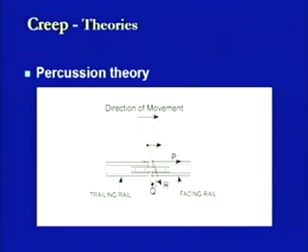Now, when this opening of the joint is created, these fish bolts will try to resist the movement of this rail section in the forward direction. When these two fish bolts are trying to resist the movement of this rail section in this direction, obviously there is a concentration of stresses at these locations, that is the locations of these fish bolts or holes. And if they become excessive, then they may cause tearing of the fish plate at this location in this direction. So, there can be some tearing on this one, and that is how it will get smashed out.